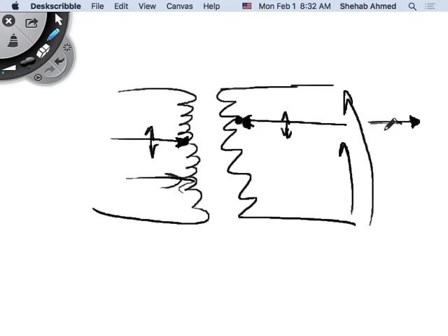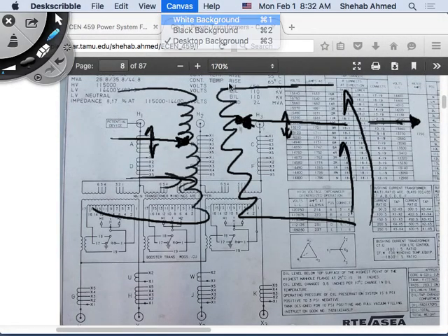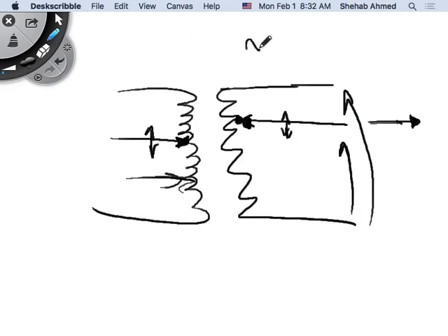So current will change. I will have arcing, right? Anytime you disconnect inductive current, we have VL equal to L di/dt. Disconnecting inductive current means I change di from a large value to a small value. So di is large in a very short period of time. I'm changing a large current instantaneously. What's going to happen? I will have a huge voltage develop across my inductor.